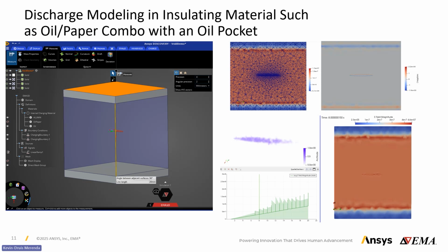This will actually tend to create a pocket of vacuum or air that can break down quicker than the surrounding dielectric material. And in this case, we can set a dielectric strength that is different for the void versus the insulator, and then understand which one is going to discharge first, and if you're getting a partial discharge in the void. And if you do, when that changes conductivity, it's going to enhance the risk of discharging the insulation inside the rest of the insulation around that void. So we have various ways to look at the partial discharge inception voltage due to these defects, as long as